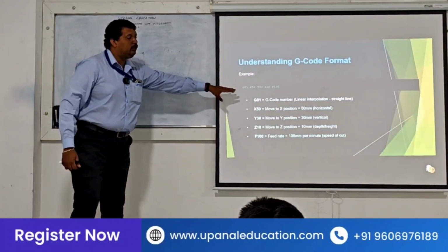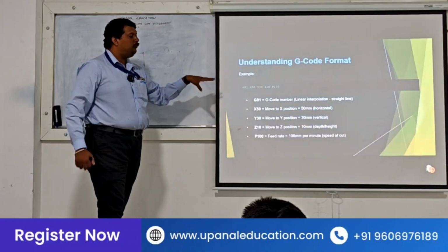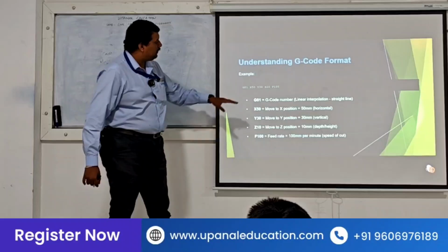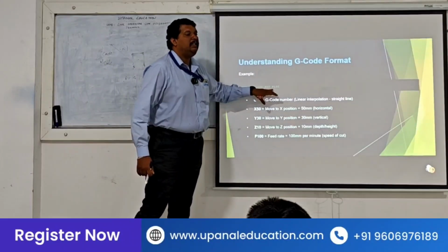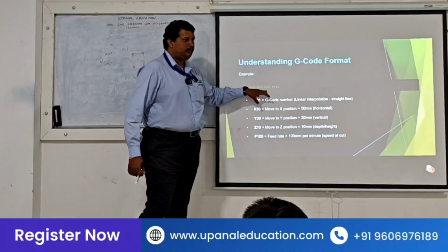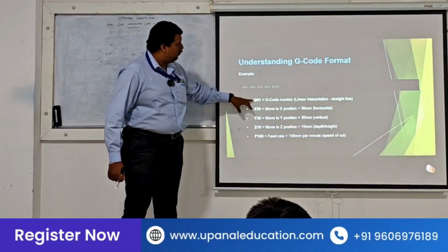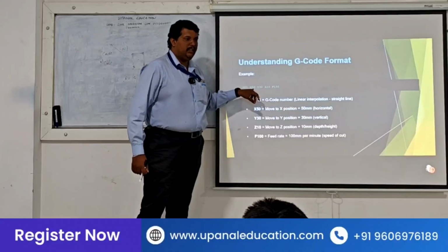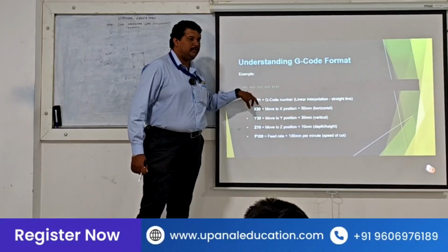G01 is given here because I need it to work there. So it should not go at that speed. We are specifying that it should go at 100 mm per minute. The feed will be given here. G01 is the G code number for linear interpolation.